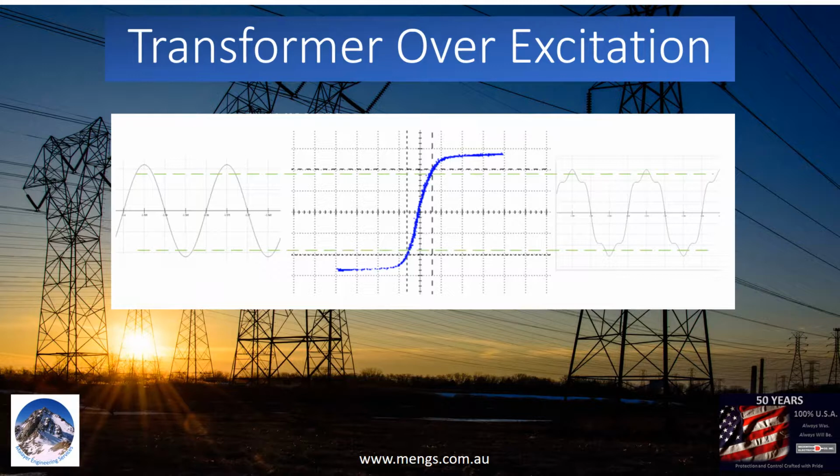Overexcitation can be a transient phenomenon. Transformers close to generators are in danger of overexcitation, mostly due to AVR overshoot or a faulty AVR. However, if transformer overexcitation is not temporary, transformer overexcitation protection should trip the transformer.